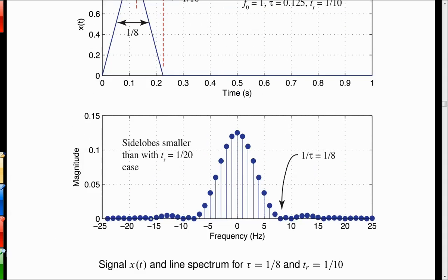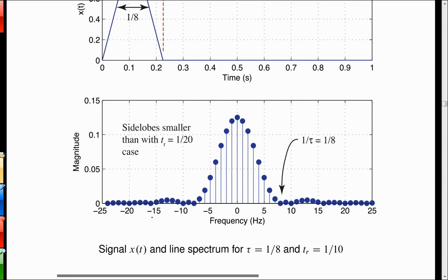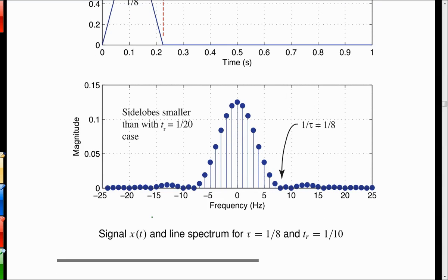So as far as getting rid of your side lobes by having less steep rise and fall time. Right. From a communications perspective, does that make them easier to transmit, or does it really make much of a difference? Well, that's a really good question. We're not going to send pulse trains. Yeah, it uses less bandwidth.